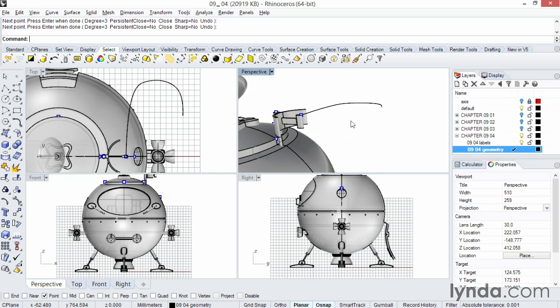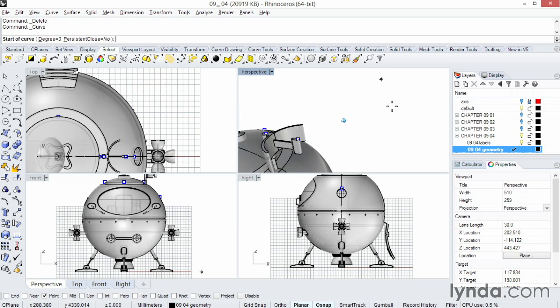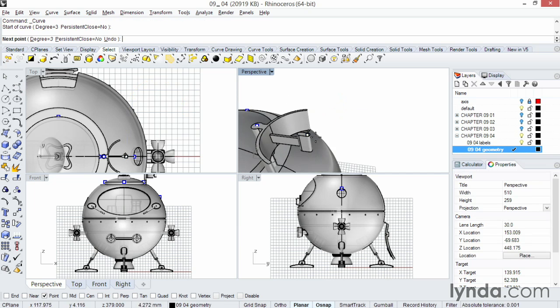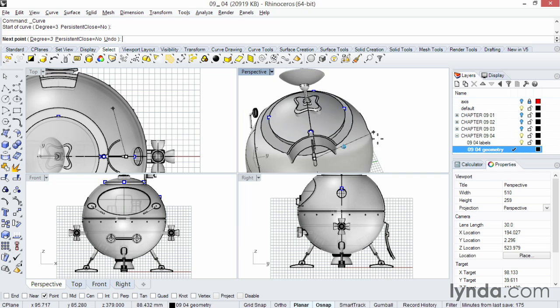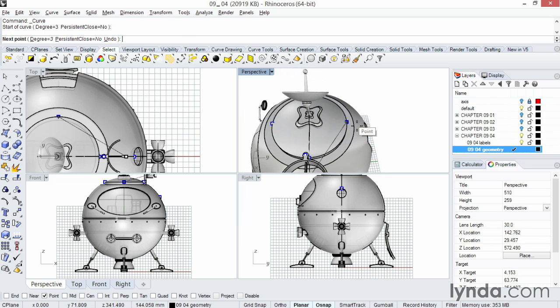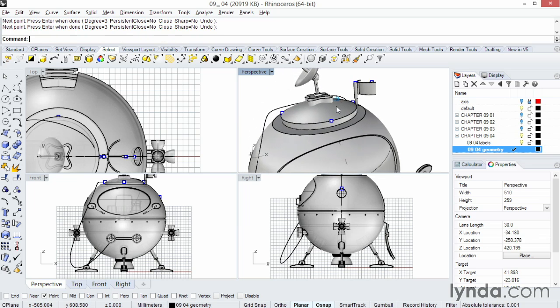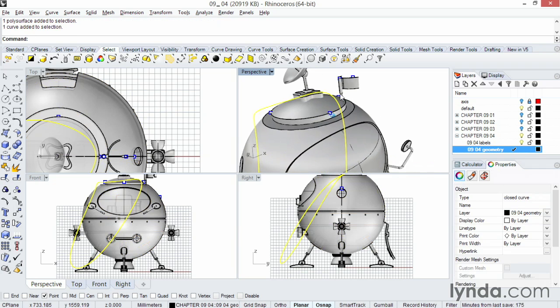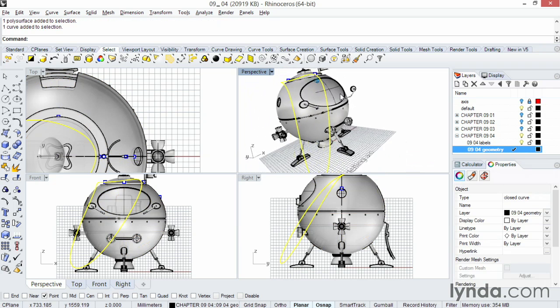Let's look at a situation where it will start snapping and pulling off the planar mode and how to fix that. So I'm going to delete that last curve and do the same thing a couple more times here. Snap to this point. Planar's on, so it should stay at the same level. But now we have a situation where other objects are attracting it and it's snapping to them. All right, so we've got a curve that is all curvy, snapping to different points, sometimes the construction plane.